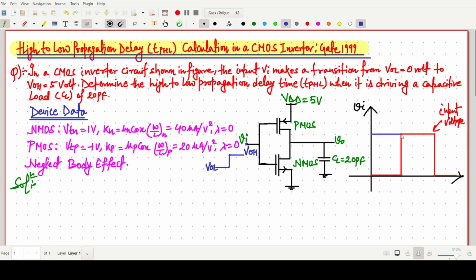Then after, when it reaches this point, then the capacitor is fully charged, and then it starts discharging, and it will go like that. Okay, and then after it again rises up. Okay, so this point we can say this one is our, say, VDD. Okay, now the middle point is our, say, VDD by 2.